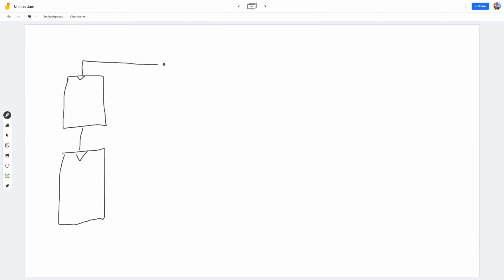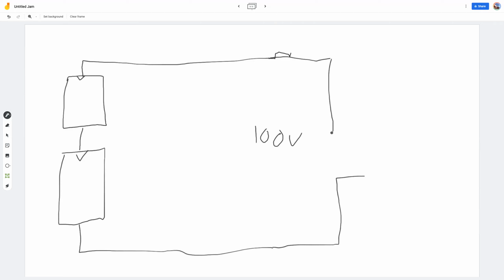We have two solar cells. Wait, I don't want to have red solar cells. Let's make an example with two solar cells, or a combination of a couple of cells, but with two groups. Let's connect both of them to a single MPPT. So with the MPPTs, we have a different way of solving the grouping issues. We can just pick the voltage of the array to be as high as possible for the MPPT. Usually you would pick maybe 100 volts, because you'll probably pick something close to your minimum battery voltage. Then you have a single MPPT that you connect to your battery.